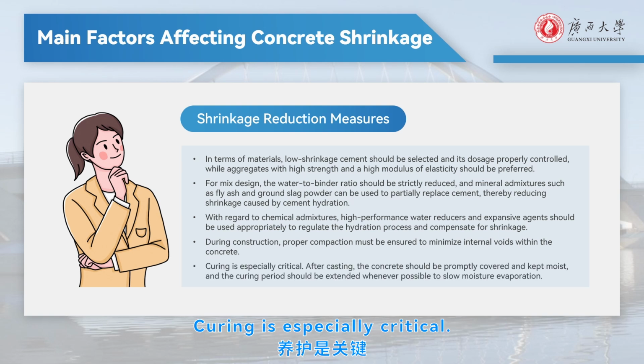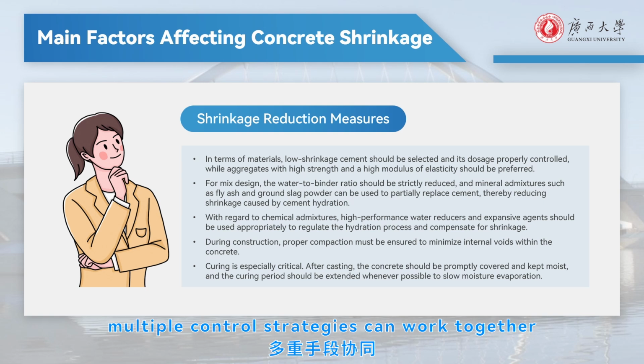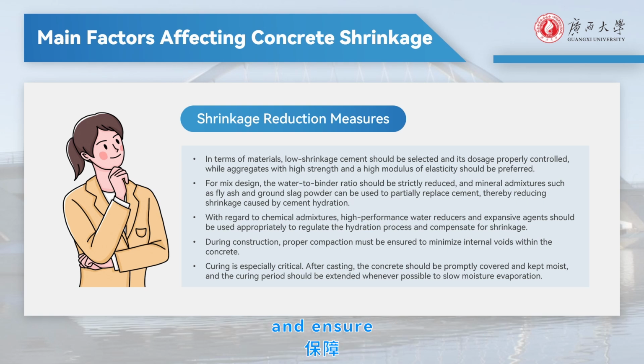Curing is especially critical. After casting, the concrete should be promptly covered and kept moist, and the curing period should be extended whenever possible to slow moisture evaporation. In addition, by combining measures such as properly designed expansion joints and reasonable reinforcement detailing, multiple control strategies can work together to minimize shrinkage and ensure the long-term durability of the structure.